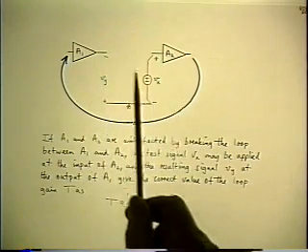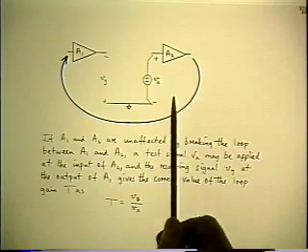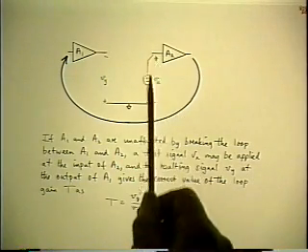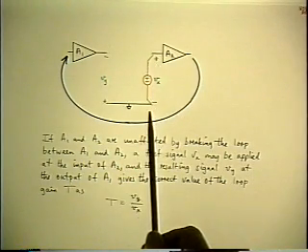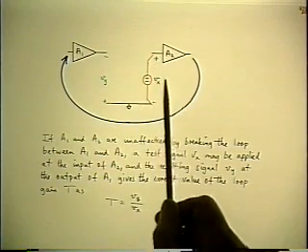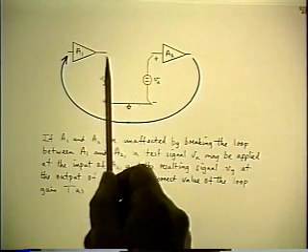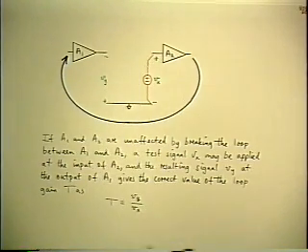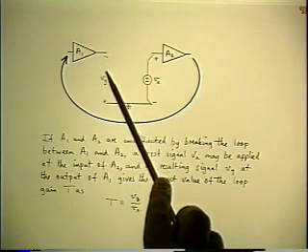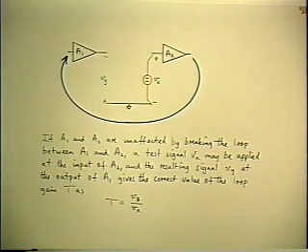So when you break the loop, the first thing you have to do is reestablish the operating point, and it takes a very fine resolution regulated power supply to do that. And even so, you spend half the time twiddling that knob and adjusting it so the other end of the loop, which is wandering around because of temperature sensitivity and gain variations, it's hard enough even to keep it in the active range, never mind at the right operating point.